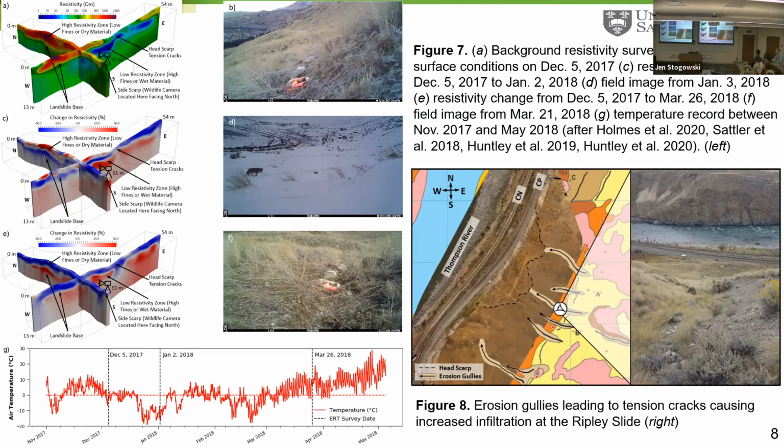The following plots show spring ground thaw and snow melt in early 2018, leading to preferential flow and deep infiltration within the headscarp. In the bottom ERT plot, infiltration is shown as a dark blue crescent that extends down to 7 meters below ground surface in the tension cracks.